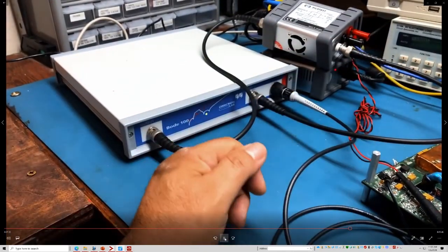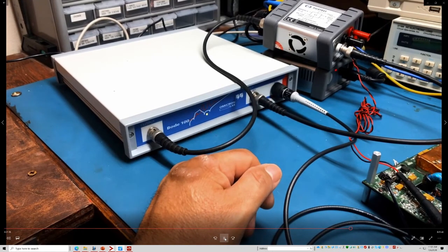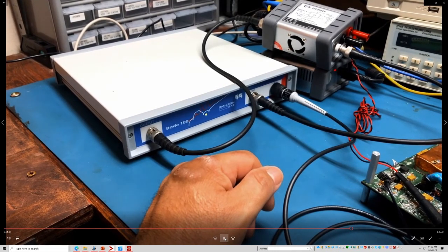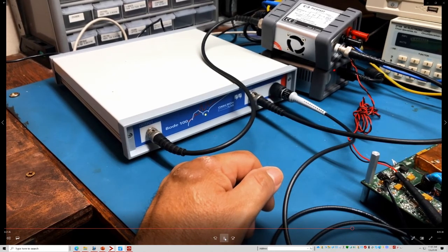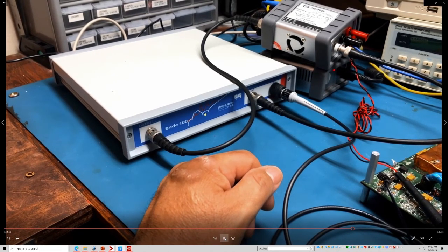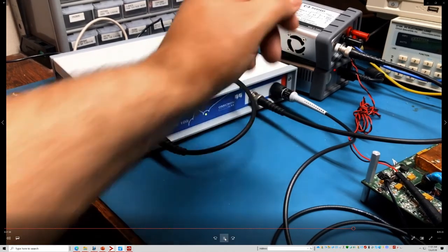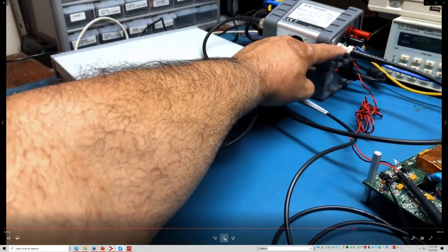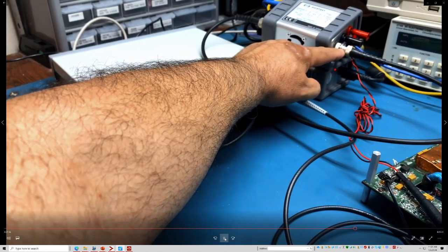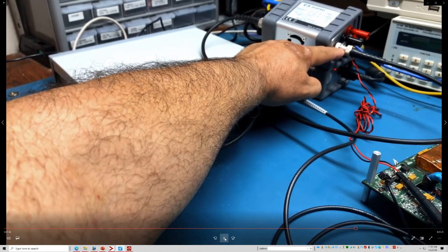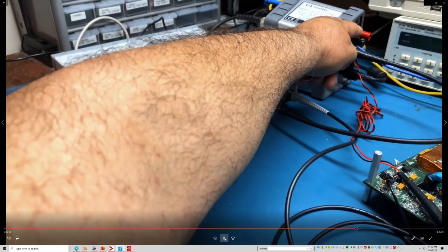Now the only thing that we need to do is measure the current. If we do voltage divided by current, then we get units of ohms. The way we do that is this Picotest injector has a current sensor that measures the current coming through the 12 volts.